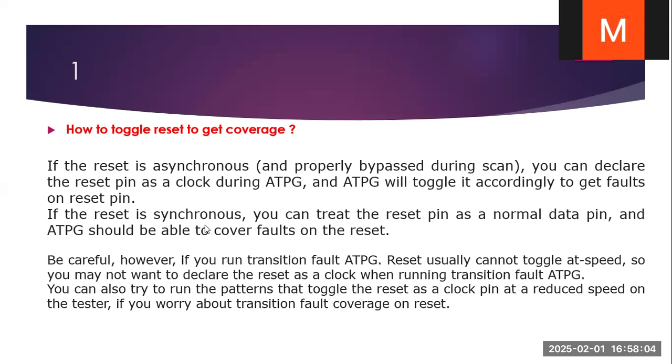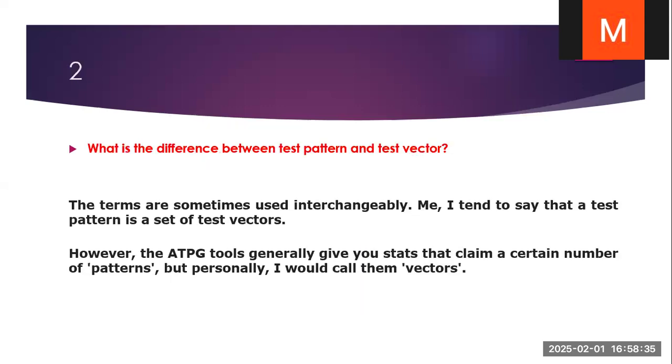Finally, if you declare the reset pin as a clock, then we are able to cover the faults on the reset pin. This is applicable only for asynchronous reset. For a synchronous reset, reset is connected to the data. You can treat the reset pin as a normal data pin, and ATPG will be able to cover the faults on reset. The next question is, what is the difference between test pattern and test vector?